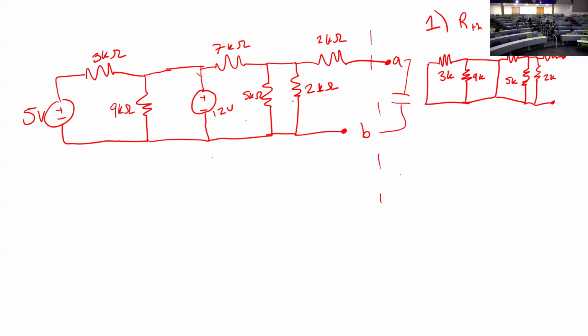All right, back to this one. Finding the equivalent resistance here. So before I even start looking at this, there's a little thing that I want to note. There's this path here, which is a wire in parallel with 2 resistors, all right? One way that you can look at equivalent resistance generally is by highlighting your nodes first. A node is if you were to take the Microsoft Paint tool and drop it on a wire, how much of it is going to spread.